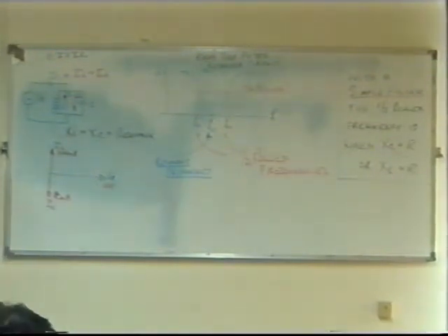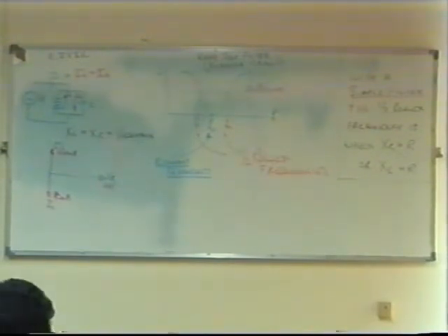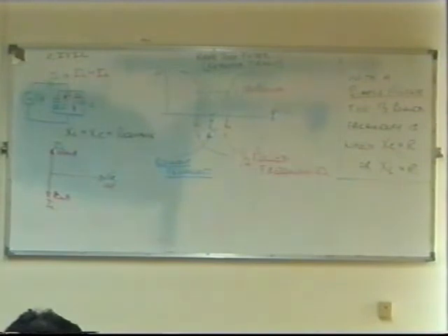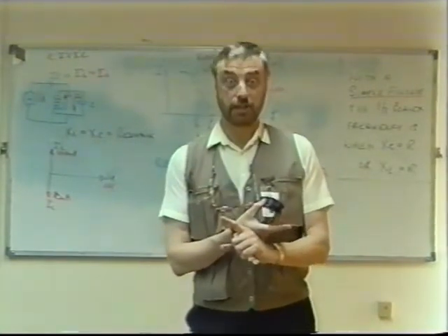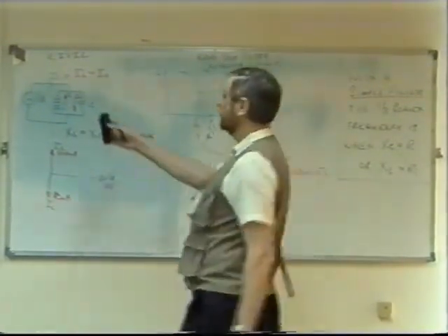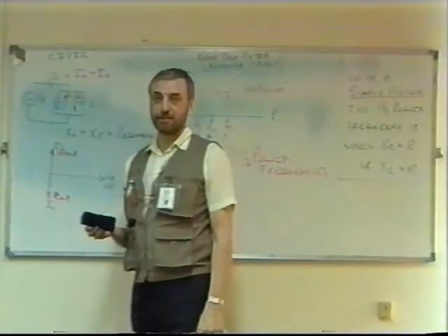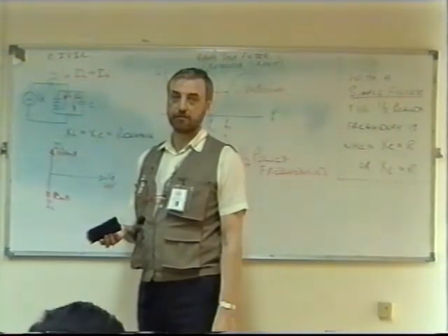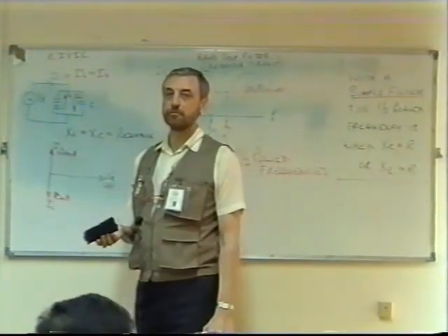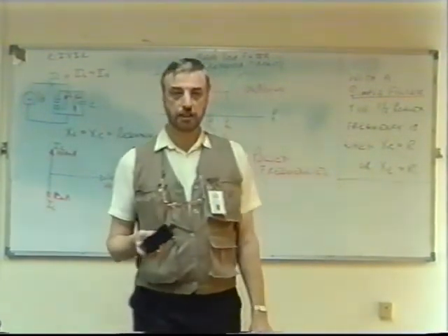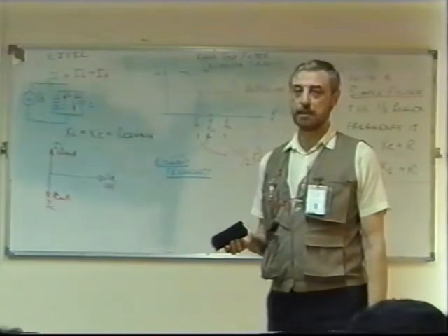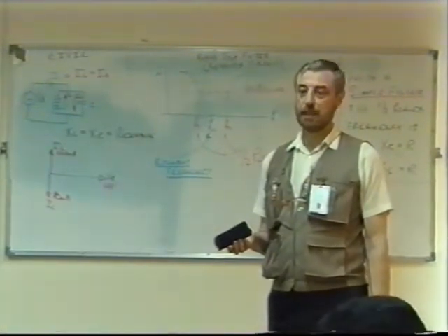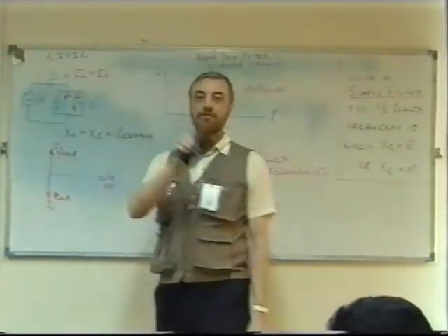Do you have another question, Fazal? About the current in the series circuit. You said the current is common. That's right. In the series circuit, we took the current as the common, and we took the differences of voltage to give us the results we wanted. Here, the voltage is common, and we took the difference in the two currents to find out what's going on in the circuit. At resonance, when XL equals XC, in the series circuit VC equals VL. Here, IC and IL are equal.